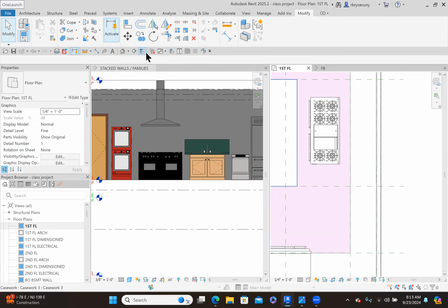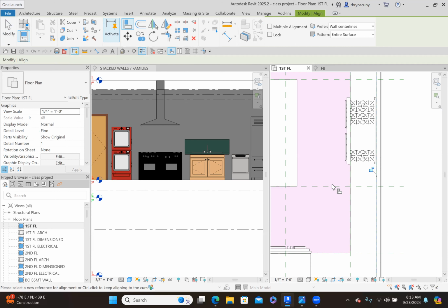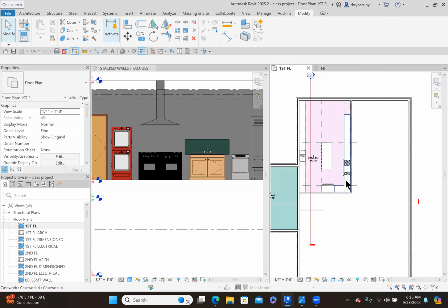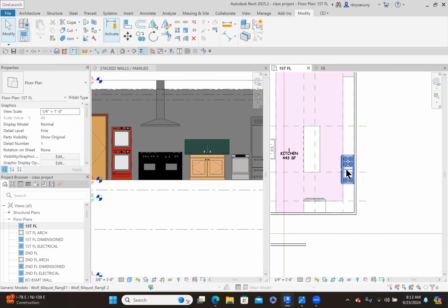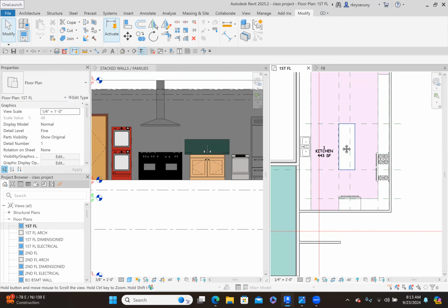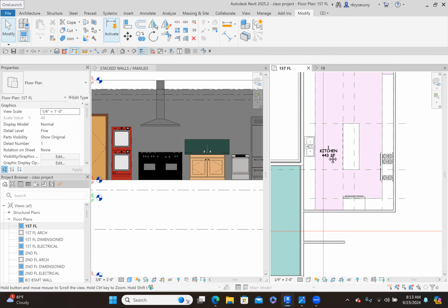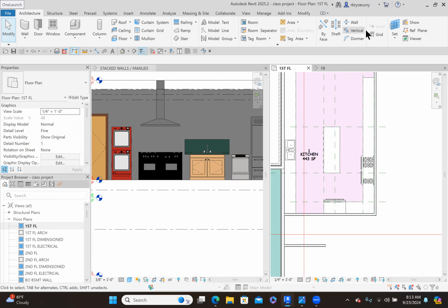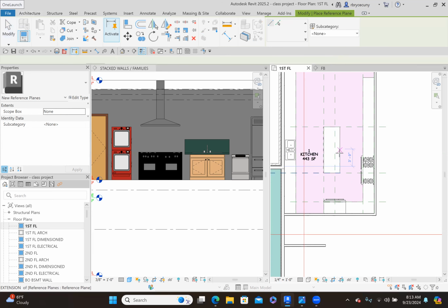Instead of putting it in by eyesight, align to the back of the wall, to the back of that. Align. We want to align to what? The midpoint. Okay. Looks pretty good. Except for the fact that this countertop is now going through the cooktop. Oh, I got it in the wrong spot. I wanted it aligned to the center line here. Oops, my mistake. And I don't see that midpoint reference plane anymore. Architecture reference plane. We're going to snap to the midpoint.